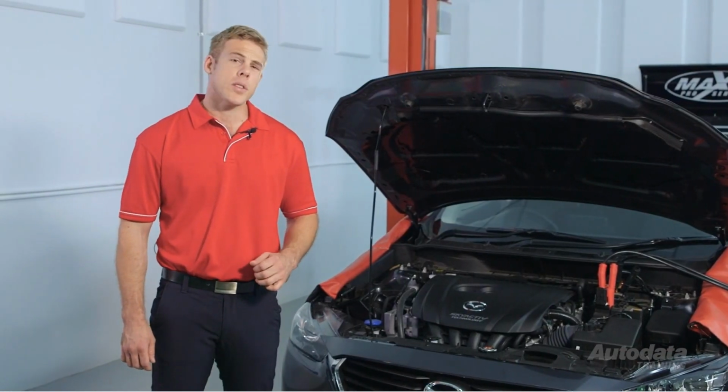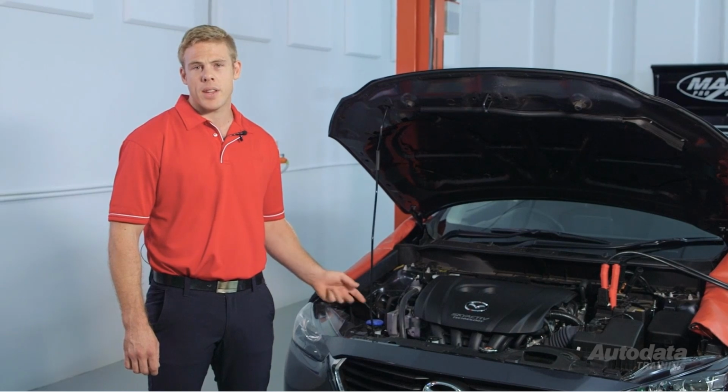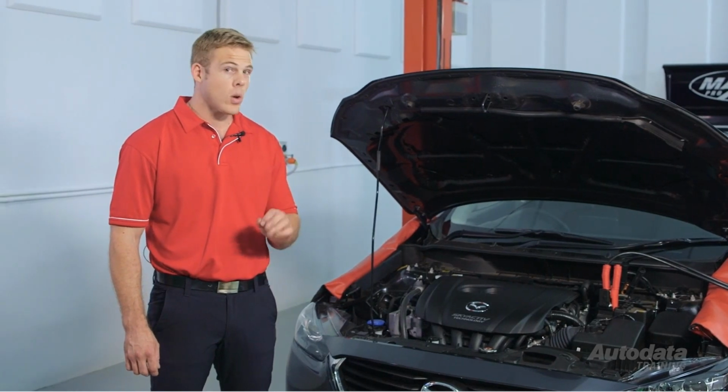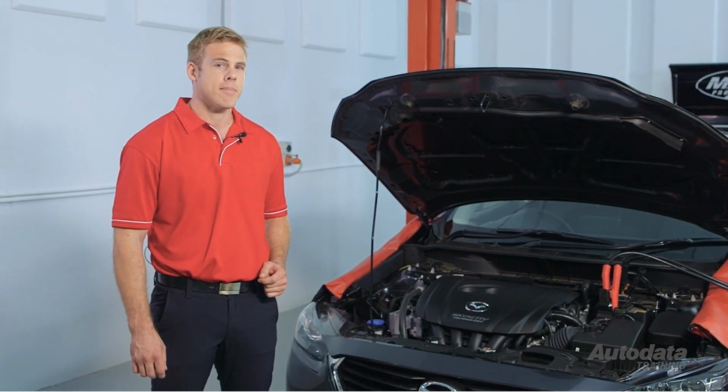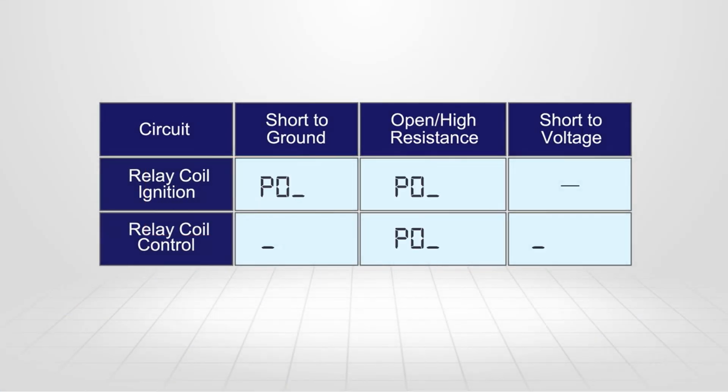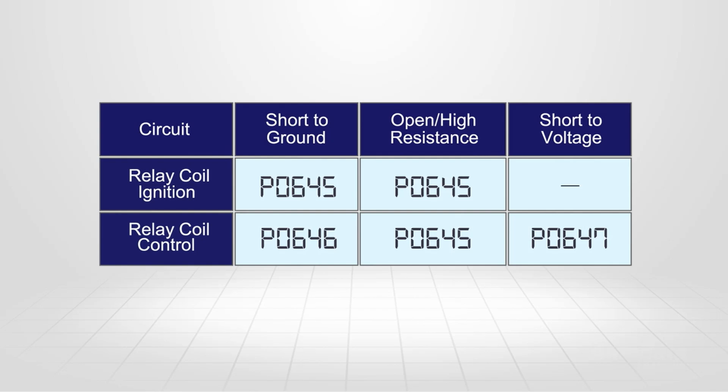So, walking to the front of the vehicle and looking down at the compressor to see if it's working is not confirmation of a correctly operating system. P0645, P0646 and P0647 are just some of the compressor clutch relay control circuit codes. These equate to control circuit malfunction, control circuit low, and control circuit high.